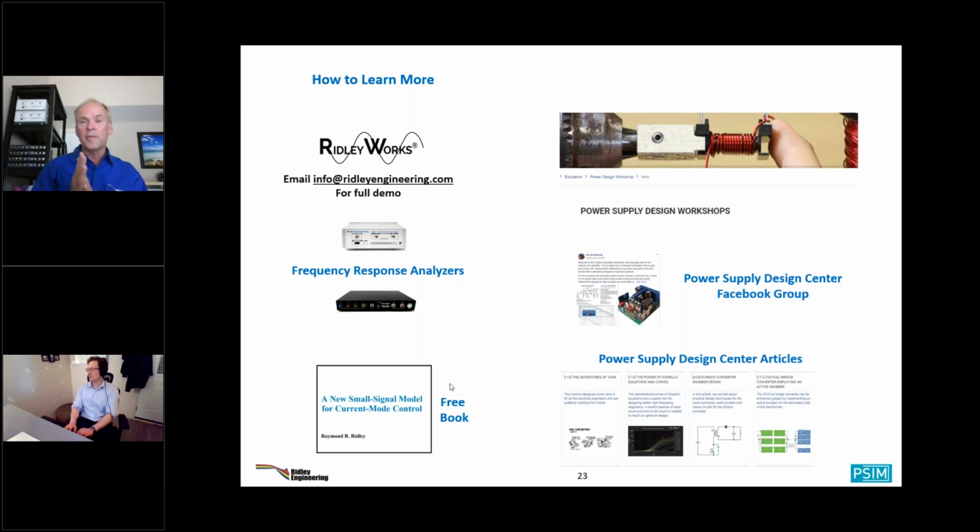So one thing we wanted to get to, we haven't gotten to right now, working between PSIM and I, is we want to have these parameter variations. Change the L over this range, change the C over this range, change the frequency over this range, and then you just set up PSIM. If it's only doing a couple of seconds for a full sweep, you set up 100 sweeps. You let it sit there and collect all the data. That's powerful worst case analysis. You present that to your manager or the contractor or whoever. He said, yeah, these guys have done their due diligence.